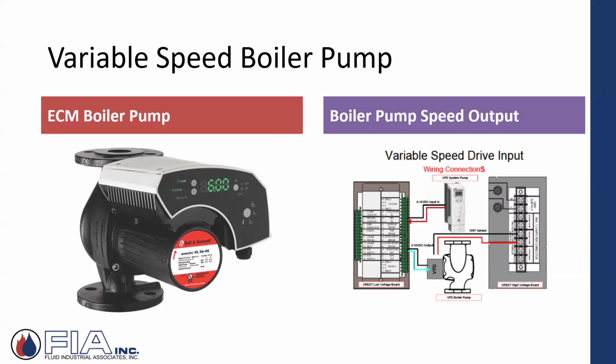And this is where it's becoming very popular on boiler pumps for these condensing boilers, X number of BTUs, 500,000, 2 million BTUs, whatever the application is. Because again, just like we talk about the maximum flow rate for that design set point, the maximum output of the boiler plant is probably needed 3 to 5, 6% of the heating season, and then something less the rest of the year.